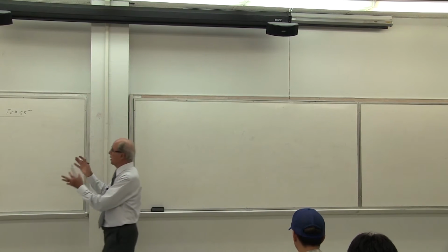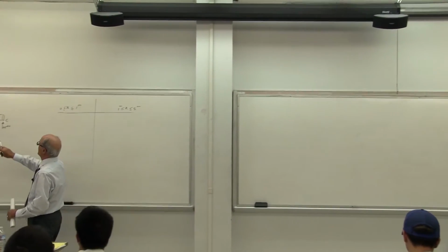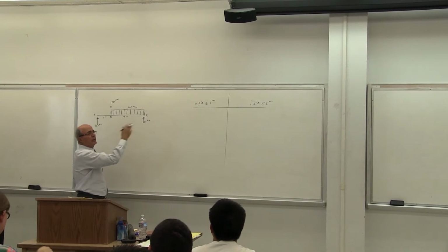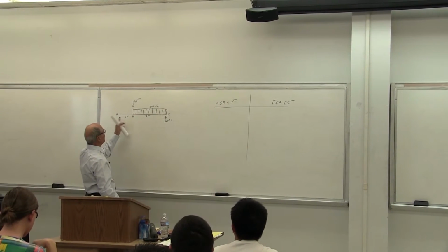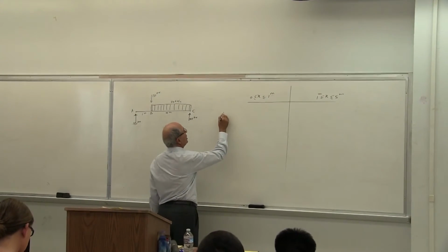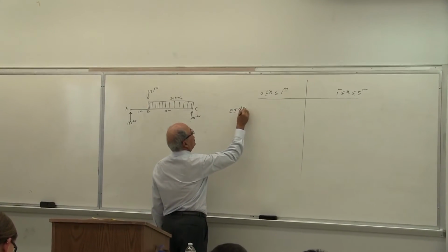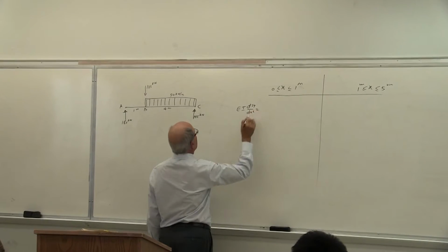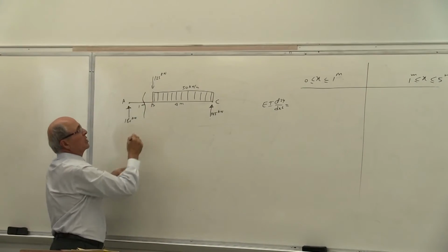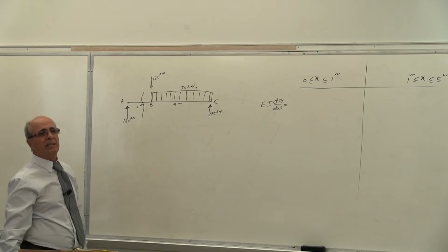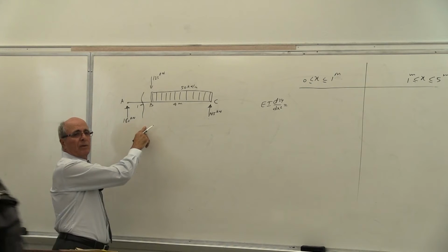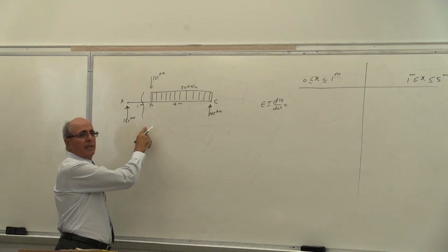Yes. First of all, it's determinate. Second, if I'm interested in deflection here or theta here, I have to do it in two parts. Otherwise, even if I do AB, there are unknowns that I cannot resolve. Anyhow, EI d²y/dx² becomes equal to the moment at this section. What's the moment at that section? It could not be simpler than that. It's 180 times x. Yes or no? Correct? Plus or minus?